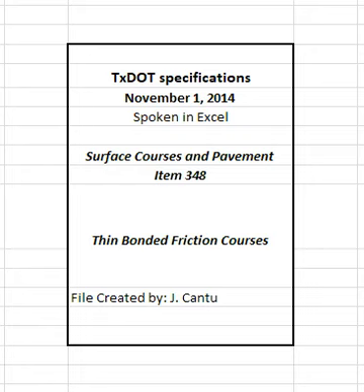3.1.2 Material Transfer Device, MTD. Provide the specified type of MTD when shown on the plans. Ensure MTDs provide a continuous, uniform mixture flow to the asphalt paver. 3.1.3 Rollers. Provide steel wheel rollers meeting the requirements of Item 210, Rolling, except provide rollers weighing a minimum of 10 tons for each roller required. Operate rollers in static, non-vibrating mode unless otherwise allowed.